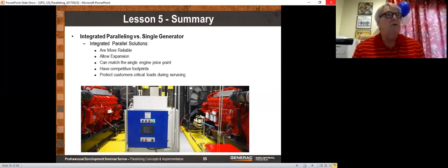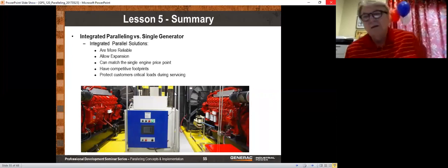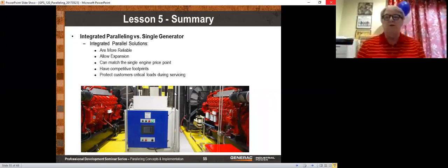Oh, okay. In terms of how often you schedule, it's pretty much the same. Regardless of the size of your generator, we typically recommend maintaining a generator every 6 months. And on the off months, you should go out every month and just check the generator. This is generally done by the user. Feel the engine, make sure it's warm, make sure the battery's good and the battery charger's on, and look to see if the controller shows any faults, things like that. That should be done monthly.